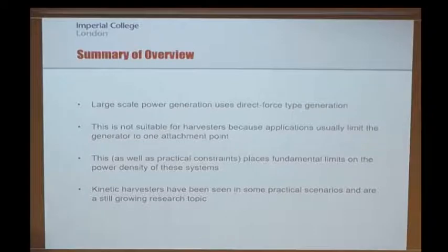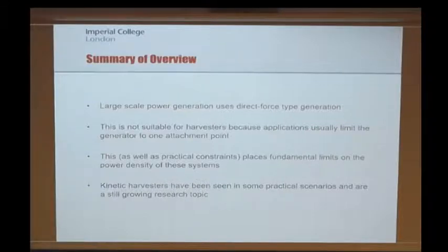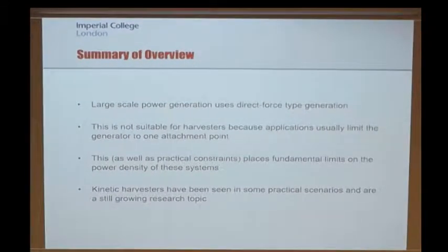What we will see actually is that there are optimal forces that we need to decide and operate on the transduction mechanism to maximize the power density. And actually this alludes a little bit back towards what Michael Lallart was saying yesterday when he was talking about these new schemes for switching the charge on the piezoelectric device. That really comes down to trying to optimize the force that is being placed onto the cantilever to maximize the overall amount of energy that is being produced.